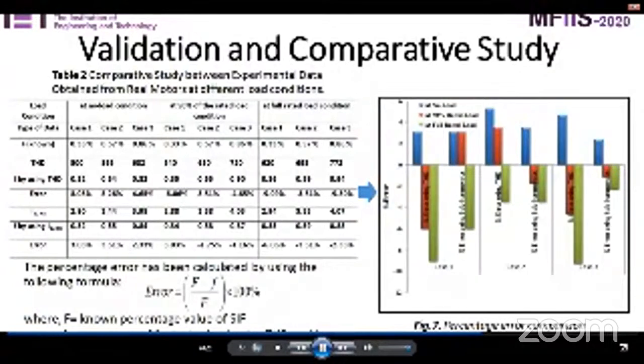The percentage error comparison has been done between the data obtained from this experiment done on real 3 BLDC motors of different specifications but suffering with very small percentage value of stator interturn fault which are of known values, and the result of percentage error comparison has been shown in figure 7, which shows that the proposed technique may be useful for such fault diagnosis of BLDC motor of different rating with different set values.